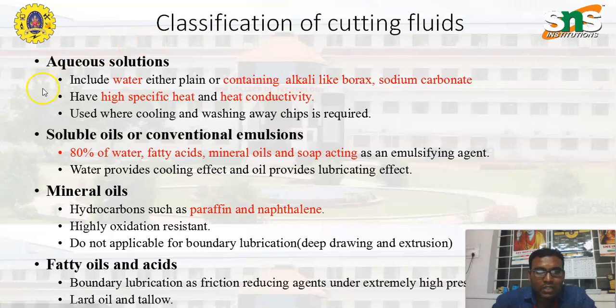The first one is the aqueous solution, that means coolant. It includes water, either plain or containing alkali like borax or sodium carbonate. It should have a higher specific heat and heat conductivity. It is used where cooling and washing away chips is required. In the case of soluble oils or conventional emulsions, it has about 80% water, fatty acids, mineral oils, and soap acting as an emulsifying agent. Water provides the cooling effect and oil provides the lubricating effect.